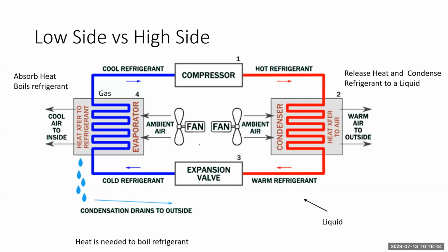And if it doesn't, either A, I had deficient or defective parts, or B, I didn't do my proper checks to make sure there was no contamination, no moisture, and that I had good voltage going to the compressor and so on. So it is a clean refrigerant system, and the desiccant or the receiver drier accumulator were doing their job. So definitely should see a long life.